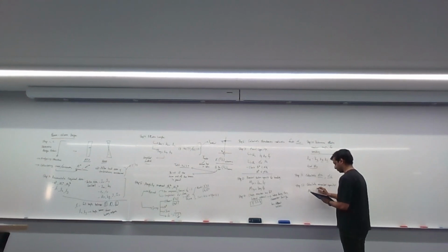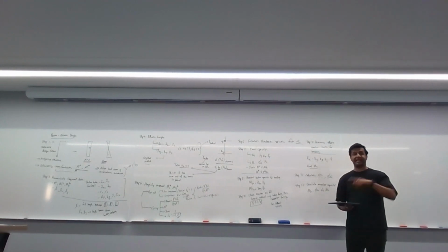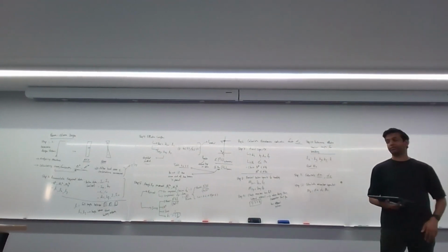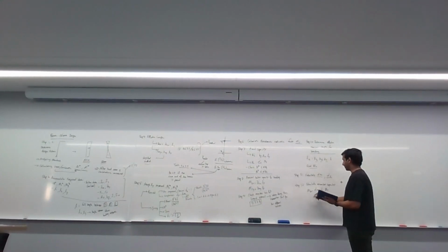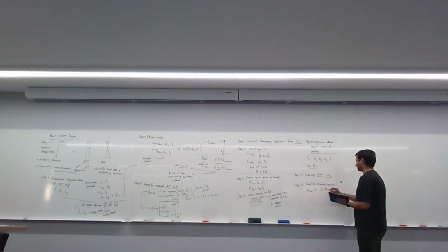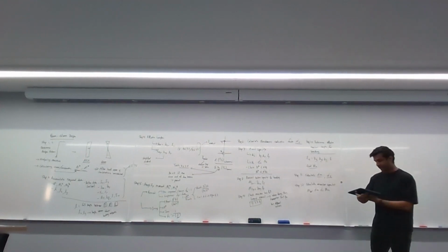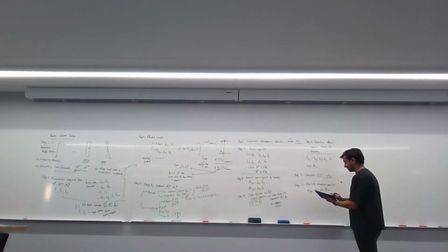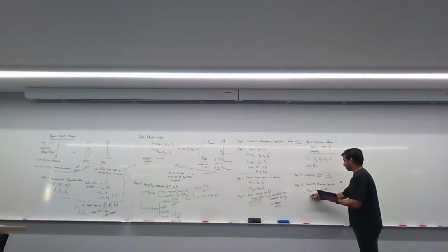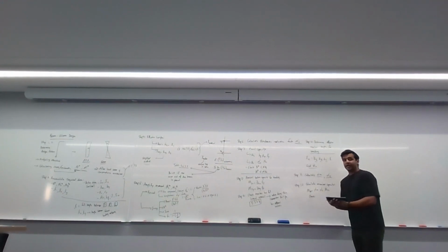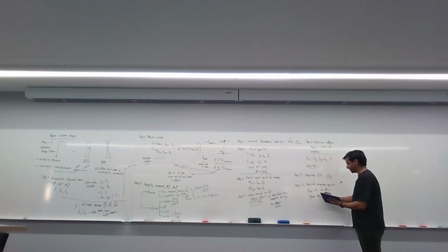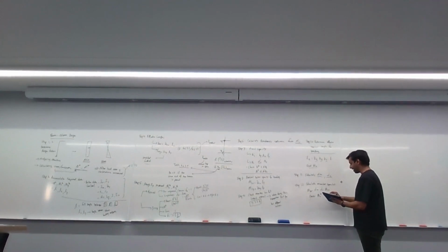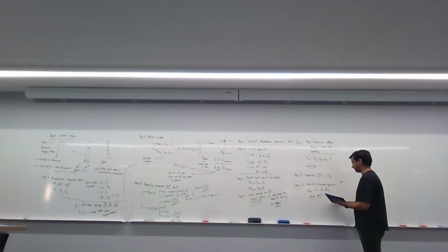MB is equal to alpha m, alpha s, Ms. Now, depending on whether it's the x direction or the y direction, you need both, right? So for example, there's MBx, for example, alpha m, alpha s, Msx. You do the same thing for y. Now, one thing you need to remember is that when you're checking against M star, remember Mx star is checked against phi MBx.